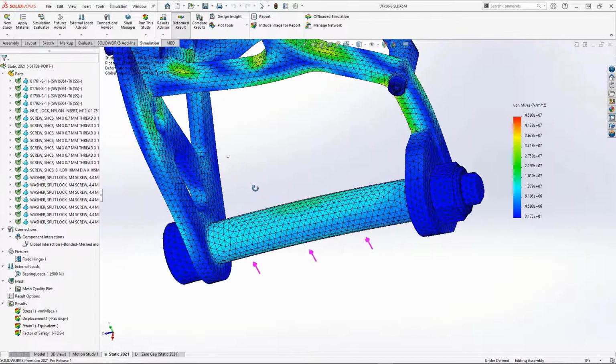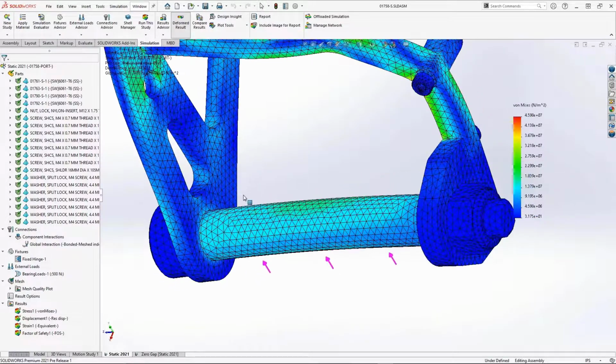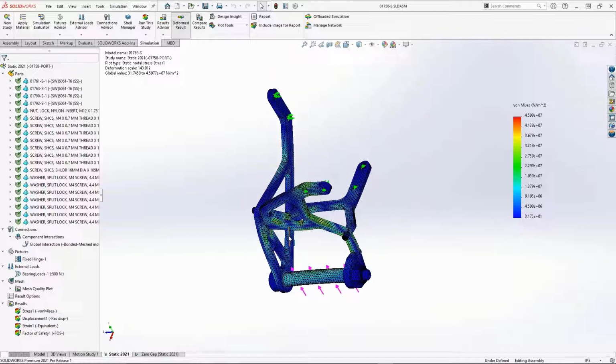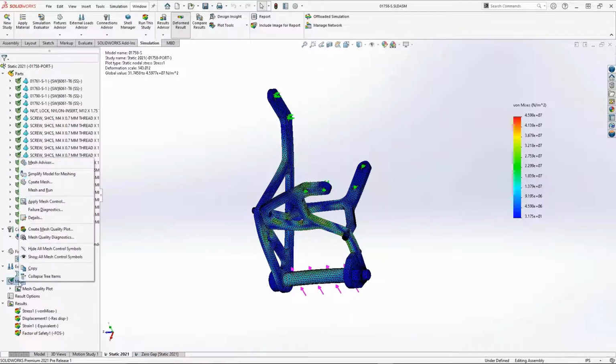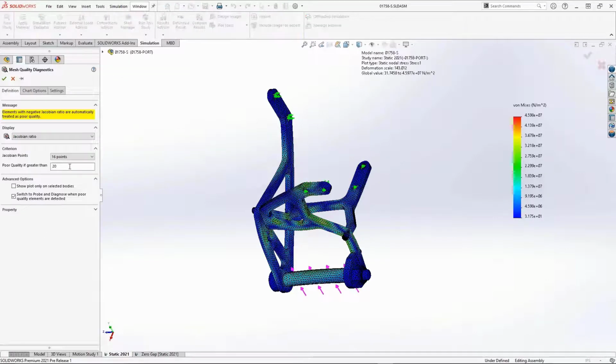For contact interactions with cylindrical, spherical, and conical geometries, correction factors are now integrated. And for bonded interactions, improved accuracy is also built in for incompatible meshes, a technology that's borrowed from Abaqus. This enables faster and more complete meshing where interacting components can't easily share nodes.